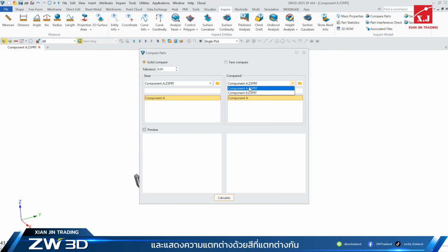To optimize the user selection experience and make it more convenient to choose between transparent objects and shaded objects behind them, ZW3D 2025 SP has optimized the Ignore Transparency function and changed it to Pierce Transparency. When shaded objects are obscured by transparent objects, you can select the shaded objects through the transparent objects. However, if there are no shaded objects behind the transparent objects, the transparent objects can be selected.